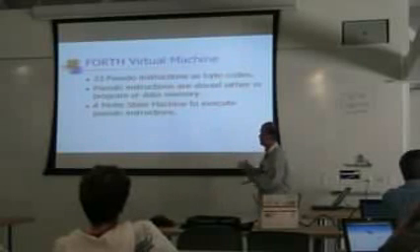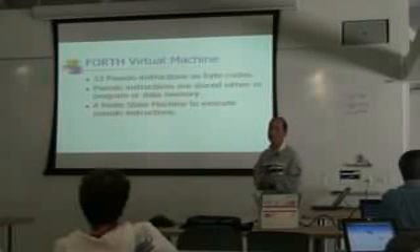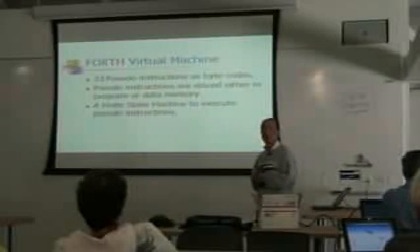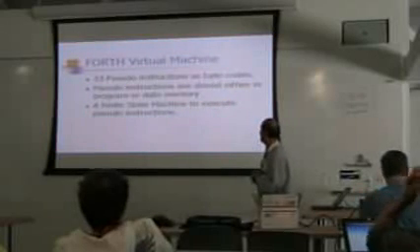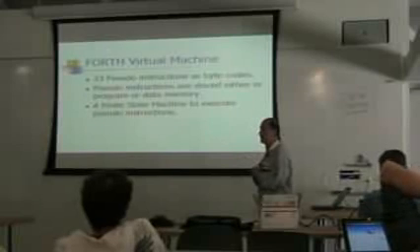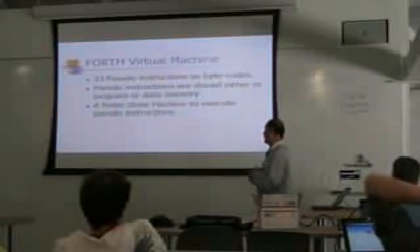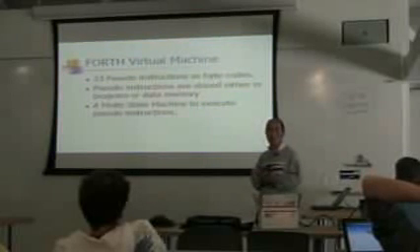Build an eForth virtual machine. This eForth virtual machine is actually modeled after the EP32, and that has its origin in MuP21, which Chuck designed originally. So basically we emulate this machine in eForth using the C programming language. We need 33, actually only 30, pseudo instructions.